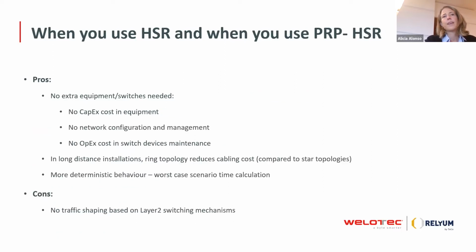Okay. So now let's switch to HSR, and I will follow the same scheme for talking about this technology. Firstly, the pros of HSR, and opposite to what I mentioned in PRP, in that case, there's no extra equipment needed. So no switches that have to be purchased, no extra engineering that has to be considered when implementing this type of system.